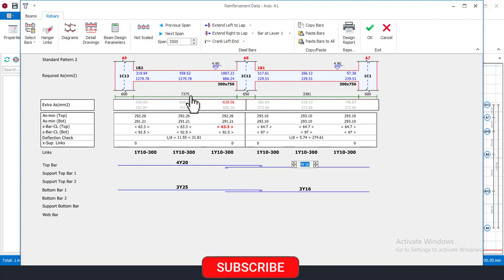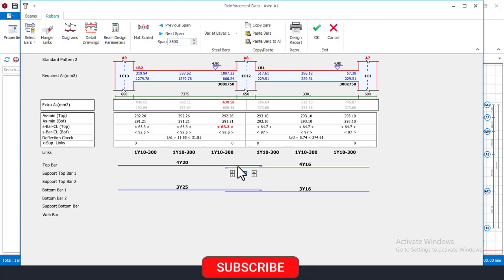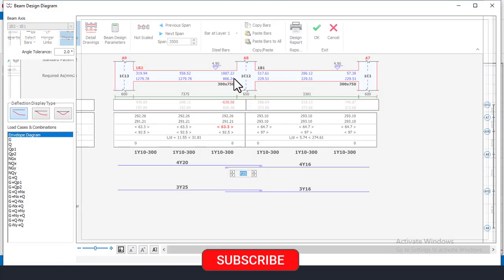This is 7.375 meters, and here is 3.something meters. So that can be used for Y16. Right now, I'll just come here and add my support bar at this place, because this support bar here is failing. And if you check our moment here, you can see that place has a very high moment.